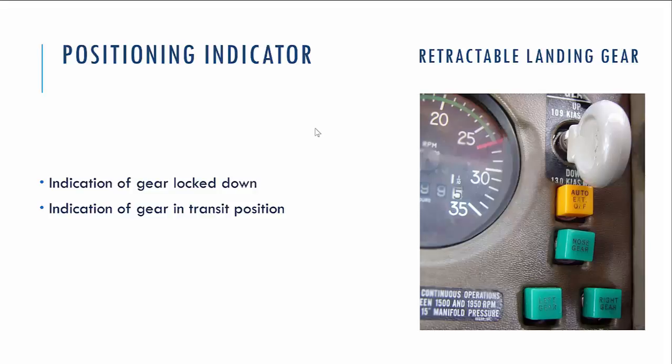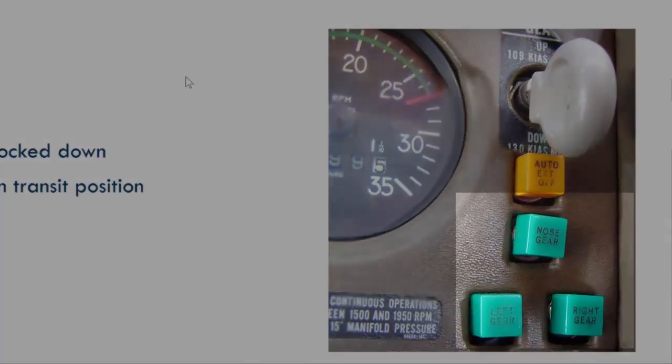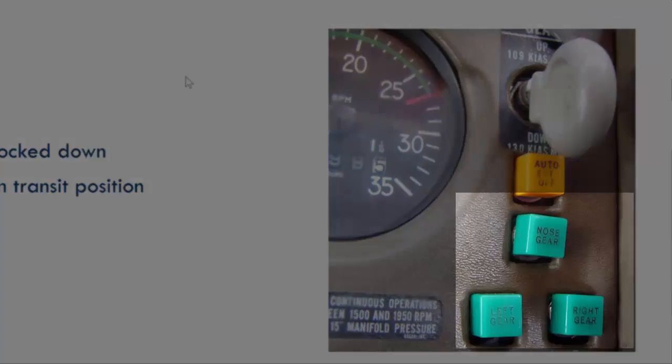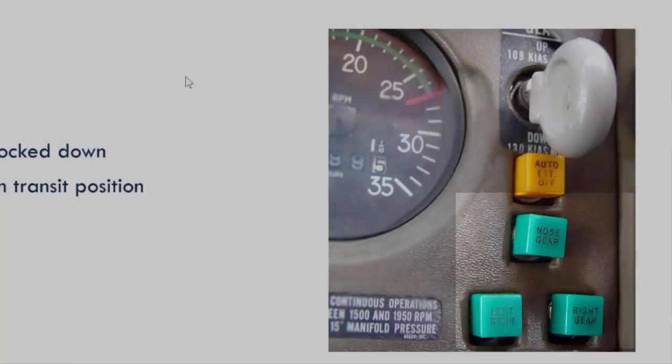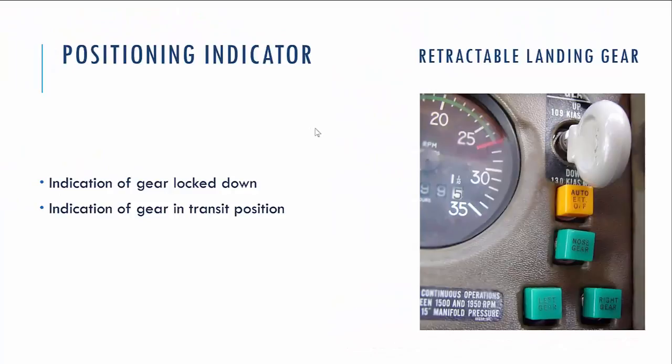To control the position of landing gears, up and down, we have control indicators on the dashboard. On airplanes like Cessna or Piper, common training airplanes, you would find three green lamps, which usually glow when gears are locked in down position. On some airplanes you could see lamps which indicate that landing gears are in transit.